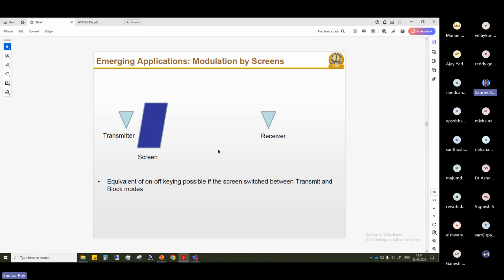Okay, so if the receiver can detect based on the signal strength, signal amplitude and phase at the receiver side, the receiver will know from which combination of the antennas at the transmit side it came. That will provide additional information. Okay, so that is why it's called space shift keying. Why space? Because the antennas are all distributed in space.